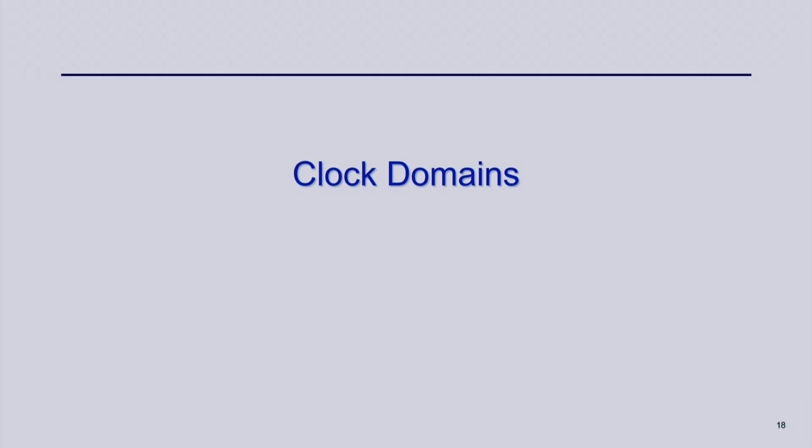So, so far we have discussed various techniques, right. What have we discussed? We have discussed clock gating, lowering the voltage, and dual edge triggered flip flops. Then I talked about different kinds of optimization techniques like RTL optimization, restructuring the multiplexer network, choosing a different architecture, clocking the control signal, or using integrated clock gating. These are all the techniques that we have discussed, and they are used to reduce the power consumption of your circuit, right.